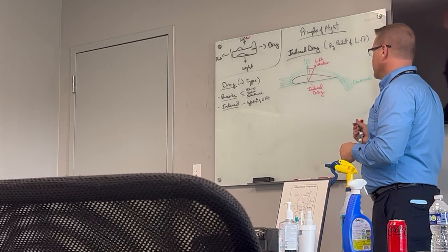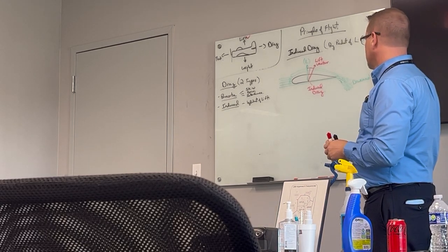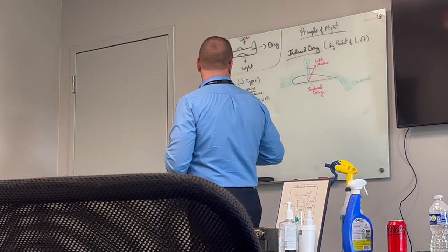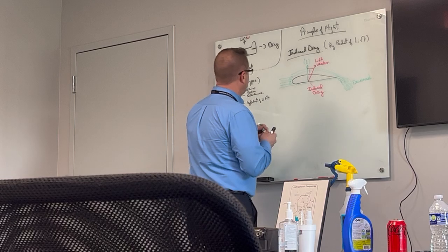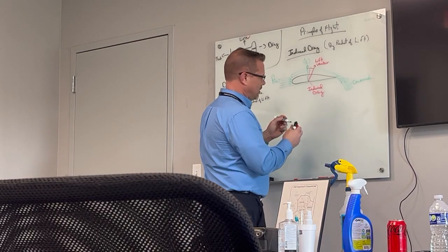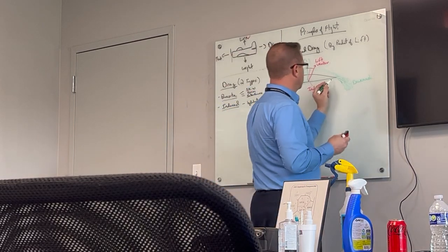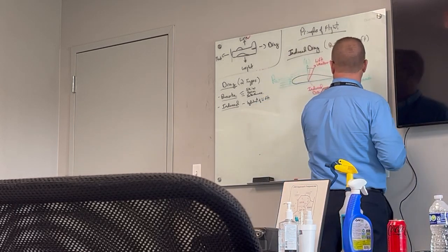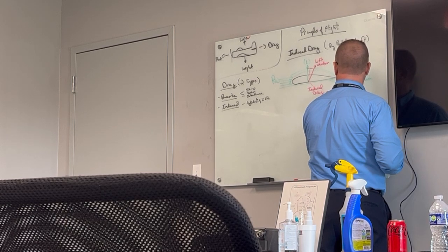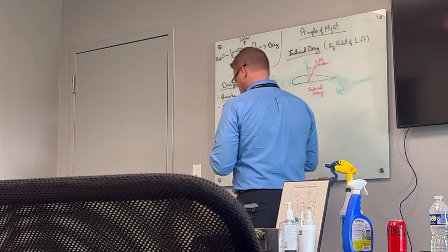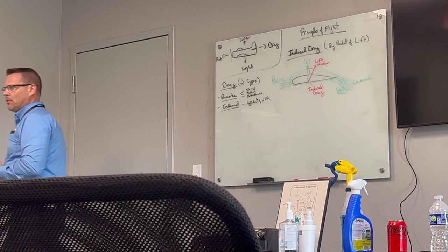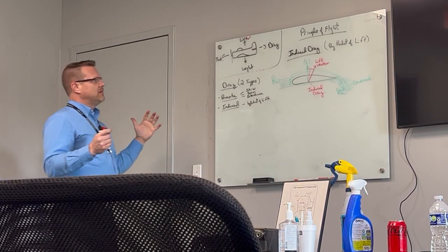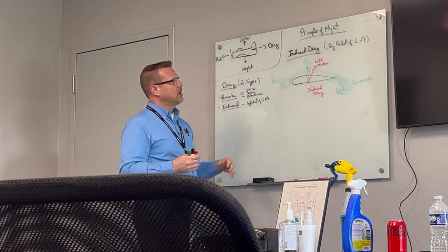One of the first things to draw on induced drag is just draw the wing again. And basically we have our relative wind, and then we have here, which kind of comes down here, and kind of gets in, and this is what we call the local flow. You want to get technical with that, downwash. So basically, as our airfoil is creating lift and this laminar flow is going over and underneath our wing,